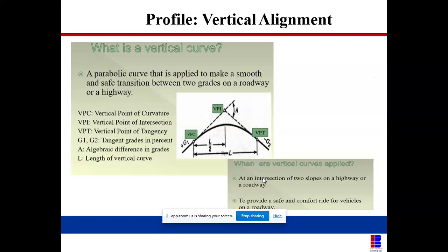But if, peradventure, you want to overtake a vehicle at that hilly area, that's why you need to maintain what they call the design speed for that particular road. Because that design speed will guide you a lot if you're overtaking. And you should be conscious as well: is the other person coming from the opposite side also sticking to the design speed? If he's not sticking to the design speed, that's when collision comes into play. That's why it's not always advisable to overtake on a crest curve, because you're climbing and you're not seeing the other vehicle coming.